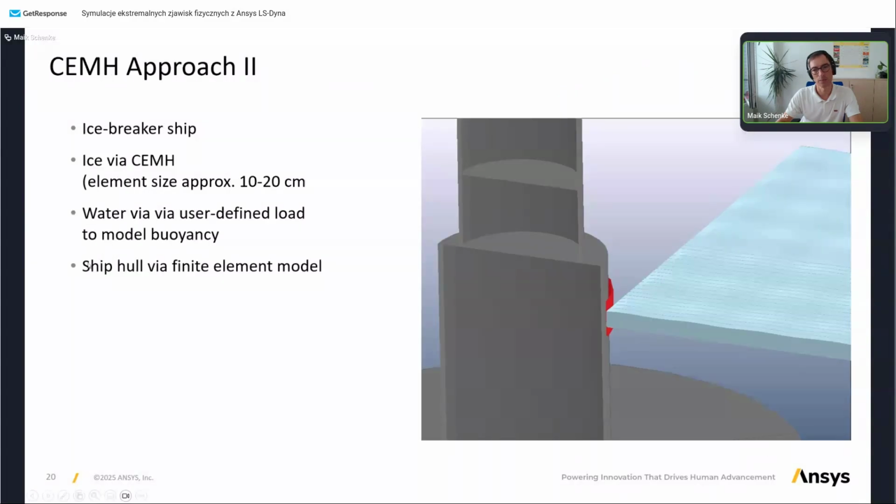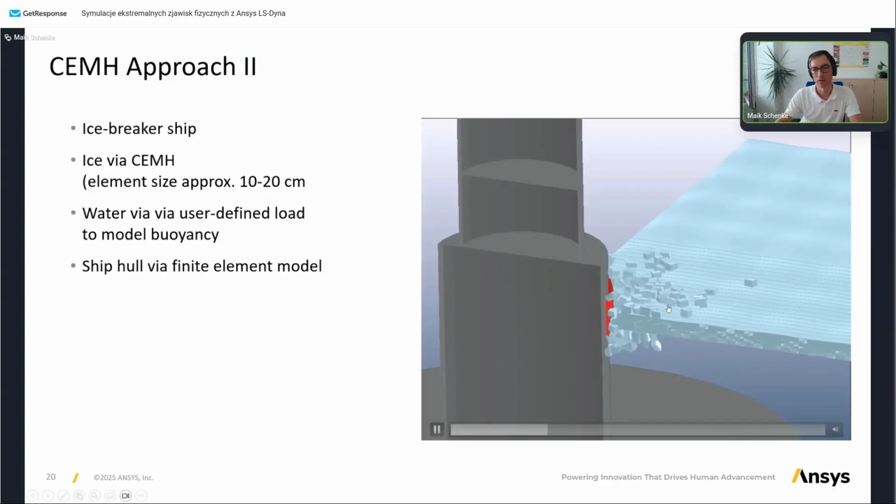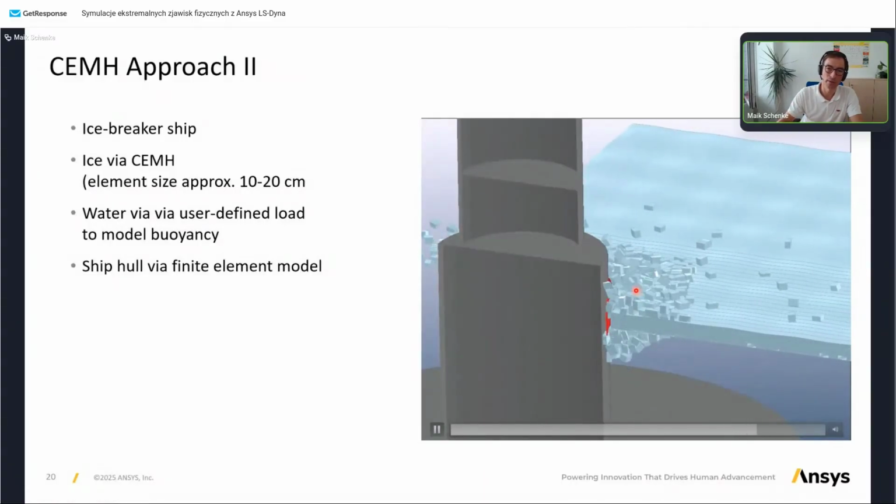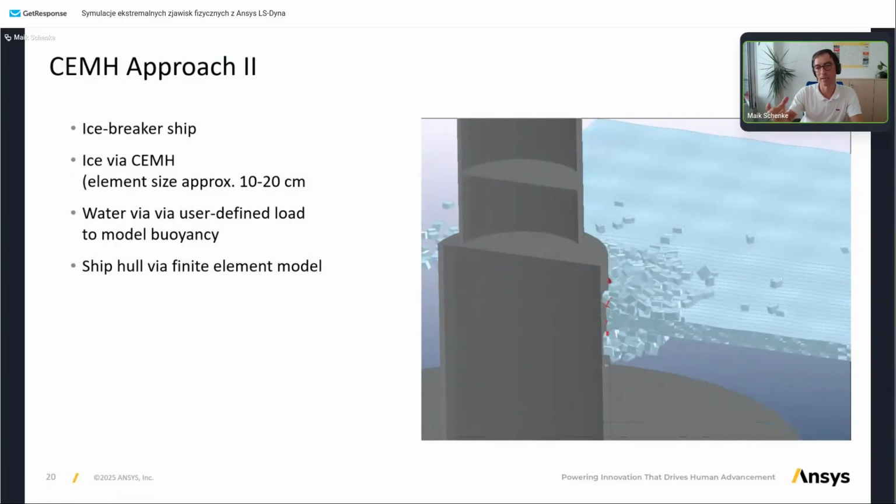If you run a simulation, this is basically a submarine breaking the ice, and this is how it looks. Now you can see the strong deformation. You can also see the failure. The important part here again is not to model exactly how the ice is breaking. It's that you need to create some load on the structure based on your physical model or based on the reality of breaking ice. So you're finding a replacement model of the breaking ice in order to get a proper representation of the load onto the structure. And I think this is a very nice and creative idea to do so.